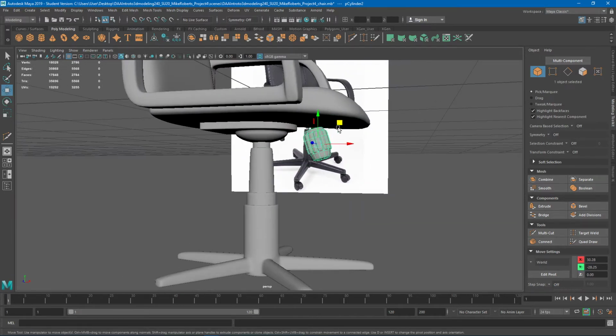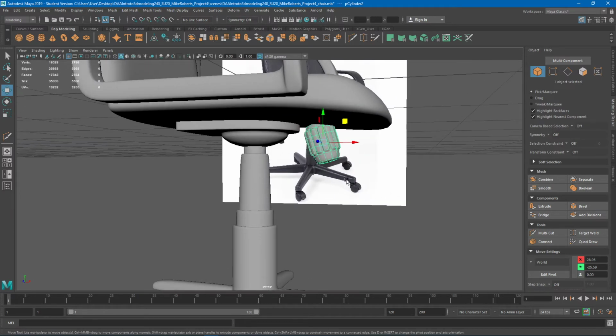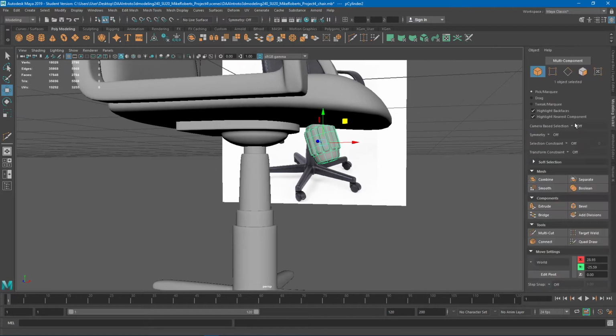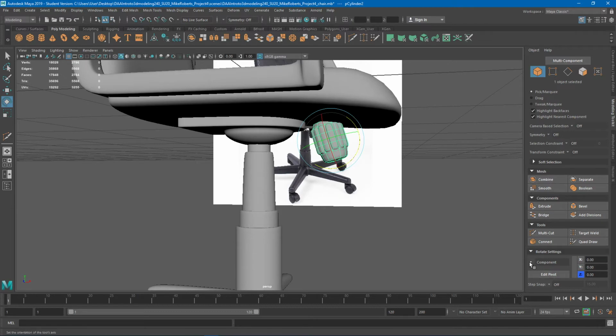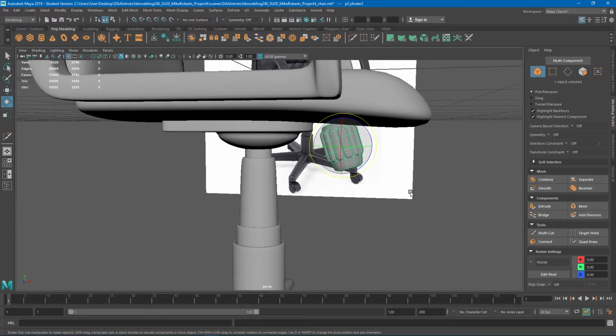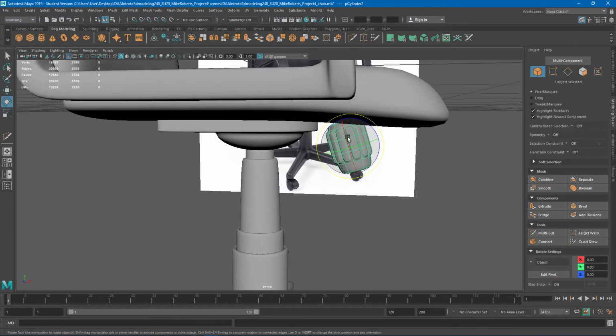And you'll notice that because I've rotated the object, the object itself has rotation. I was rotating the actual object. You'll notice that particularly if you were to set to world. World lines it up to the actual world axes, and that's a good default. You're going to use that a lot of the time. But object actually lines up to the object's orientation. So it's like world, but for the object itself. If you've rotated an object, that's what object does.